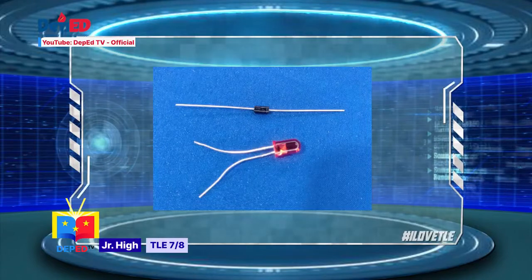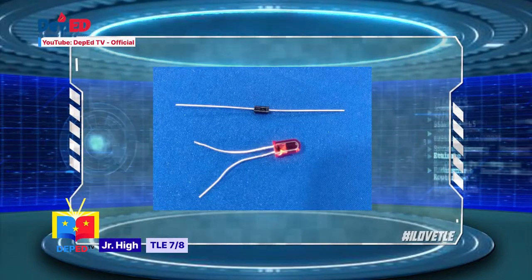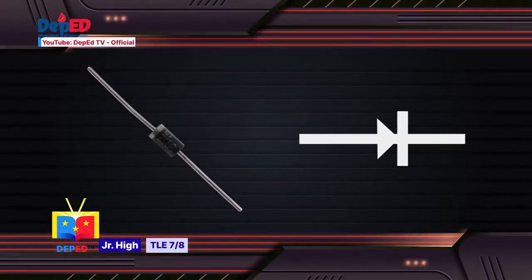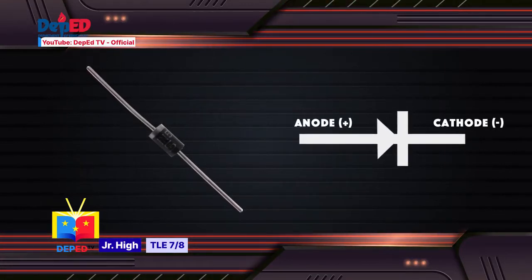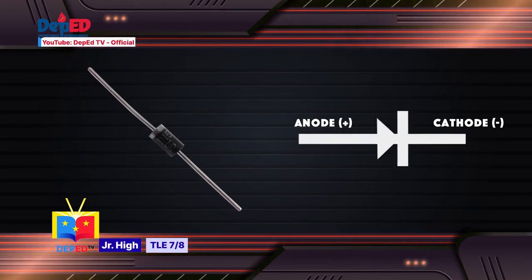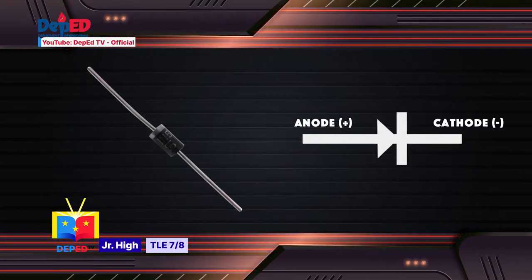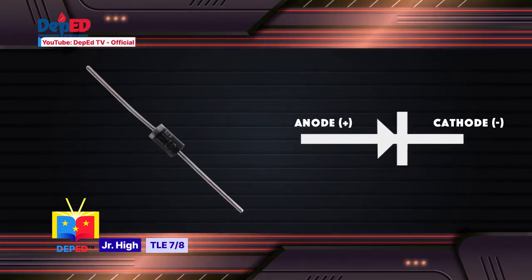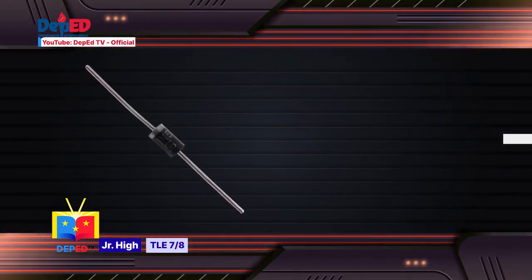Diodes are semiconductor devices which are used to convert alternating current to direct current. The two electrodes or terminals of the diode are called anode and cathode. The symbol of the diode is shown here. The arrowhead points in the direction of the conventional current flow in the forward biased condition. That means the anode is connected to the positive side and the cathode is connected to the negative side.